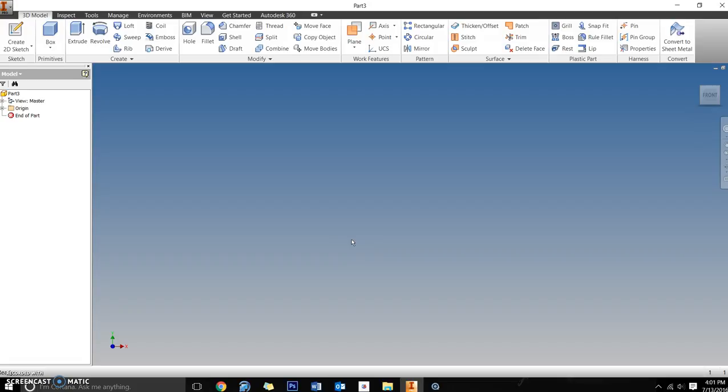Now remember, the parameters for your airfoils can't be any larger than 3 inches in length and 1 inch in height. You can go as far as making it about 2 1/4 inches in length and anywhere between 1/2 and 5/8 inch in the thickness of the airfoil itself. I recommend nothing smaller than that because it's going to get very hard to fabricate and drill it. So think about that, and hopefully you already talked to your instructor about some of the positives and disadvantages of different design choices with thickness and length.